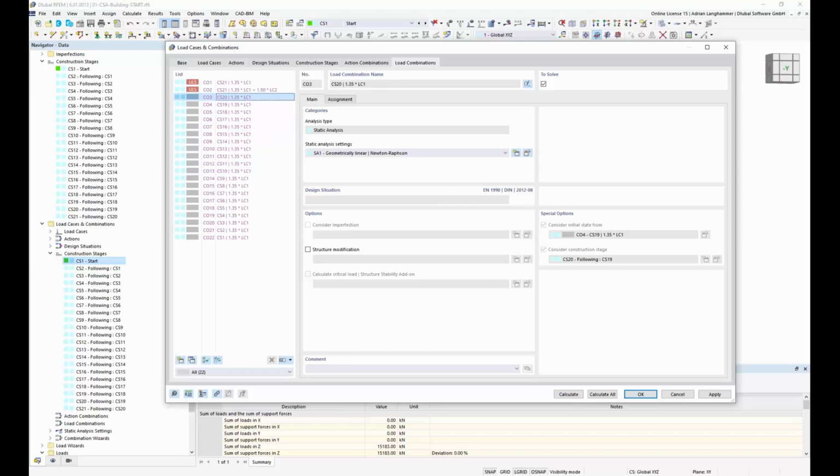And then the program needs to generate some auxiliary combinations where it's possible to consider the load case with the used factor for the combinations. The normal stages calculation would be performed with 1.0 permanent load, and here for the combinations the construction stages need to be calculated again with the factor 1.05.